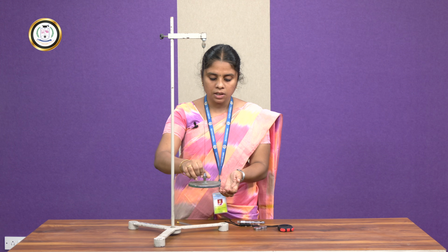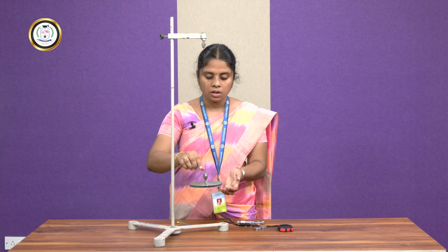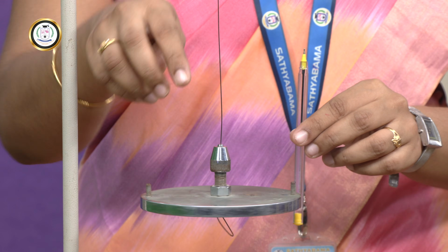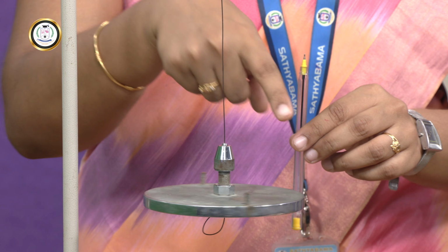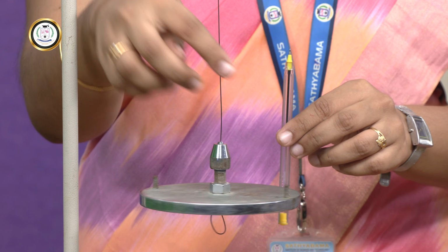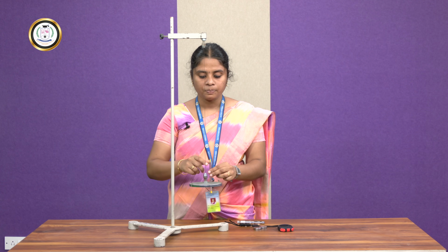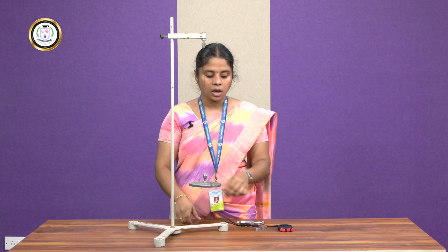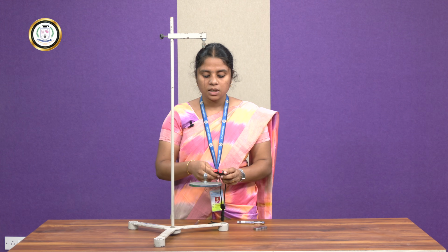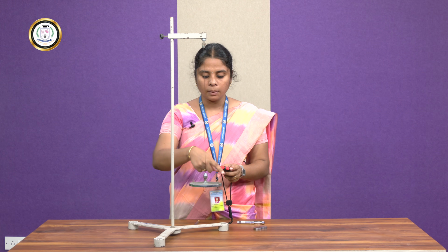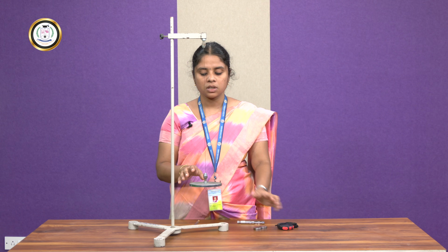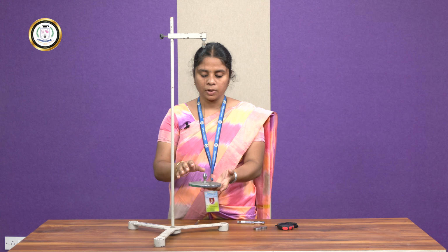So now again give a certain amount of force to this disc. Now again the disc starts to produce torsional oscillations. Have a pen, see the position, this knob goes to the new position, again comes back to its original position. This is torsional oscillation. Now again start the stopwatch. See what is the time required to complete 10 oscillations. The time taken now to complete 10 oscillations will be our trial 2 measurement. So, that is our position A.